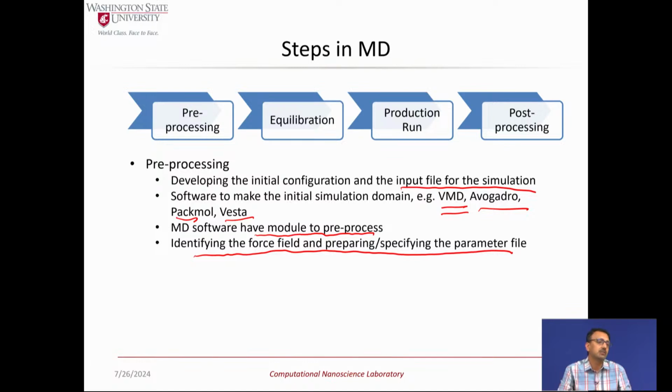The system blows up a lot of times because your Verlet algorithm is unable to use the time step you have specified to integrate the equations of motion.